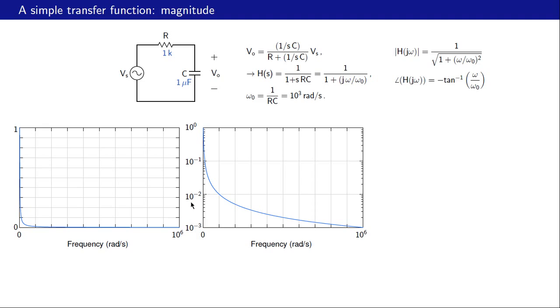For example, let us take omega equal to 2 times 10 raised to 5 radians per second, that is here. And now we can read the value of mod of h from this curve. So somewhere there. What is that value? So this is 2 10 raised to minus 3, 3, 4, and let's say it's 5. So something like 5 times 10 raised to minus 3. This was not possible to do in this older plot because the y scale had also got compressed here.